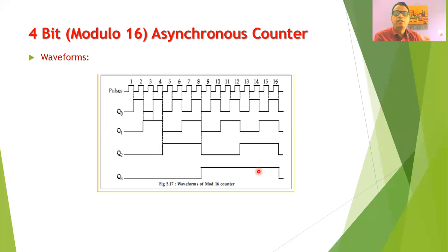An additional NAND gate is required, which is connected to the clear input in such a way that whenever the 10th clock pulse appears, the circuit resets to the initial state 0000. So it is possible to construct such odd counters where the count is not a power of 2.